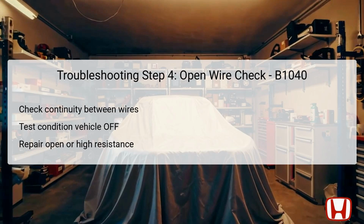Next, conduct an open wire check on the wiper line. This involves checking for continuity between the designated test points with the vehicle in off, lock mode, and the wiper control unit connector still disconnected. Specifically, measure between pin number 2 of the wiper control unit and a body ground.